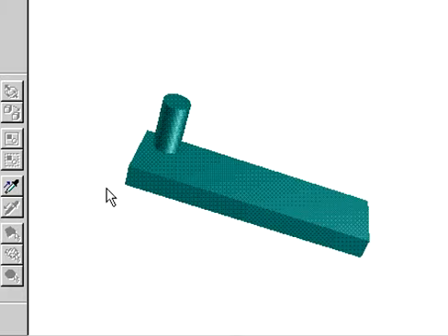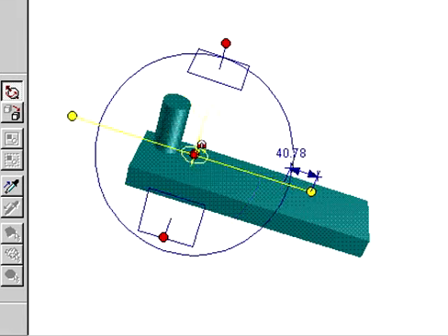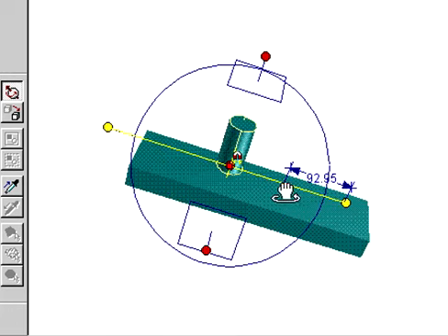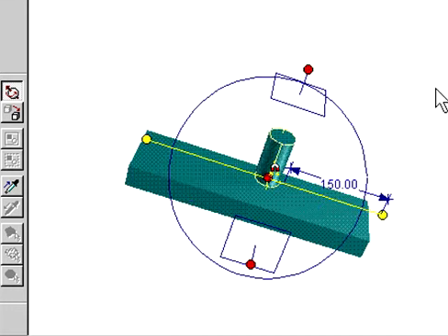The TriBall is a universal 3D positioning device. To work with it, select a shape or model and then choose the TriBall tool. To move the object along a single axis using the TriBall, click and drag one of the handles. To move the object to a precise location, right-click the position value and select Edit Value. Enter a new position value and click OK.